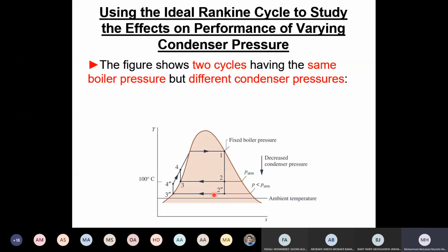So we can reduce this here, but when we reach 25 degrees here, we cannot because I am cooling this by ambient water, liquid water, at ambient condition. And therefore, the limitation here, if when you go to this pressure here at 10 kilopascal, you find it 40 degrees centigrade. I cannot reduce more below than ambient temperature. So this is the limitation here.